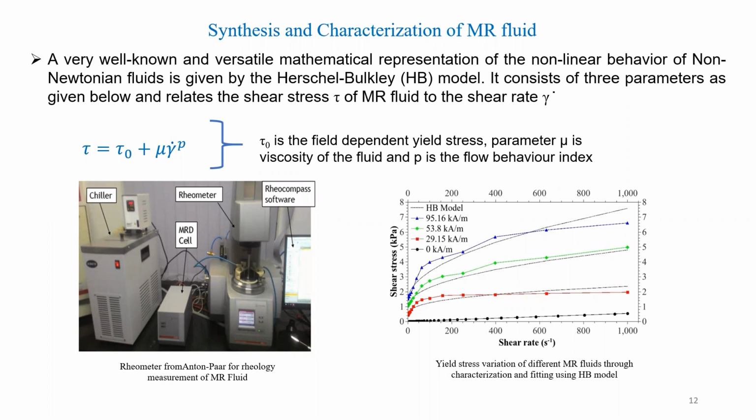It should be compatible in terms of viscosity and temperature, because most industries use silicon oil, and if you substitute some other oil, it should have the same or near properties as silicon oil. We have to keep that in mind while preparing the MR fluid. These are all the properties I already explained to characterize the MR fluid. So this is the first step, preparation and characterization.